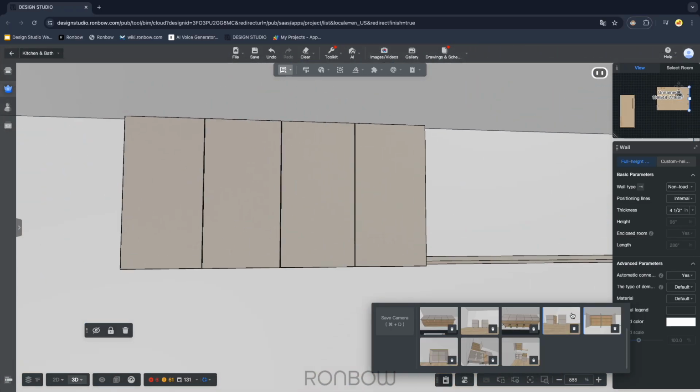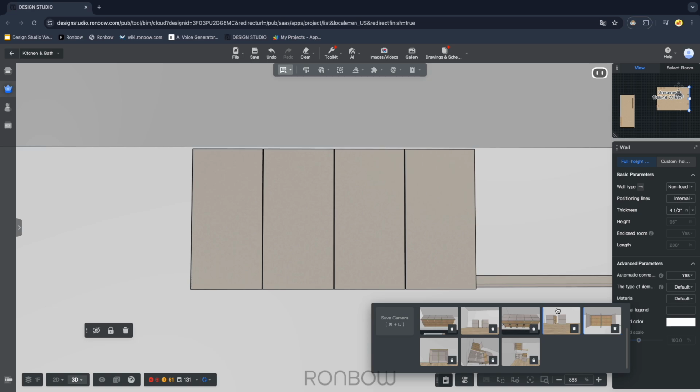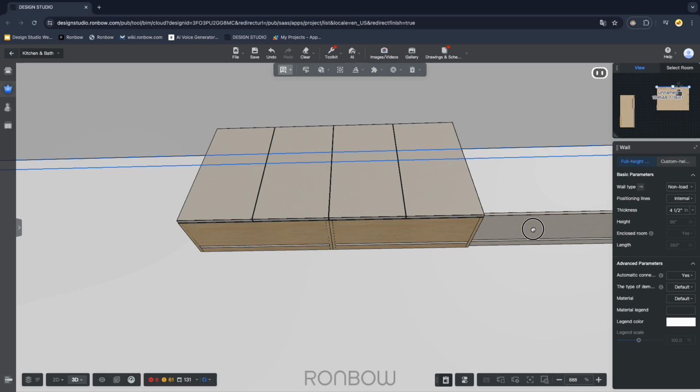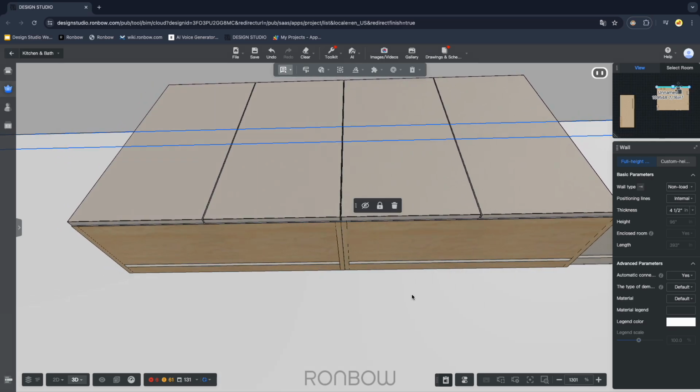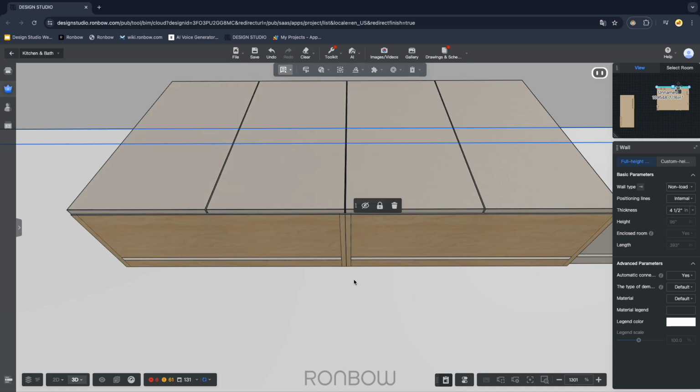Wall cabinet LED options are similar to those for open box LEDs. It's important to note that our bottom LED option only routes through the bottom panel and does not notch the side panels. If you want to achieve continuous LED lighting on the bottom of wall cabinets, you have two options. The contractor can notch the side panels on site to allow for the installation of continuous LED lighting. Or you can apply a horizontal panel that spans multiple wall cabinet bottoms.